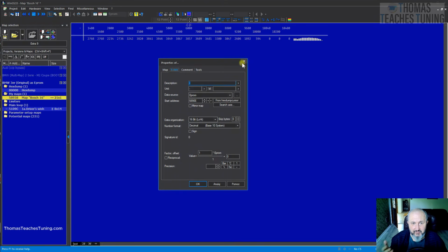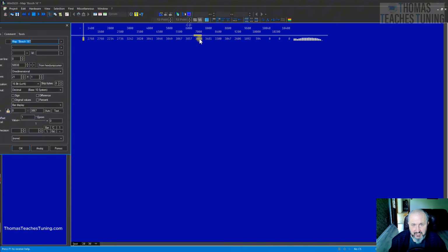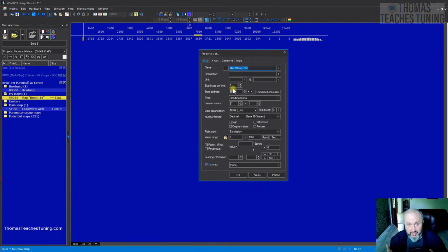Next I enter the map and assign the appropriate name. I double click just into the map, ensuring not to click where the axis is, as that would lead to editing the axis properties itself. To avoid mistakes, I always click in the data area in the middle. Sometimes it can be narrow, one line for example, but still I click in the data area. Let's call this map 1B, ensuring I'm in the correct location within the main loop.